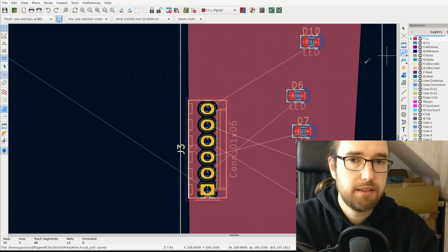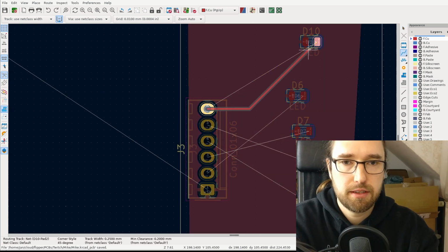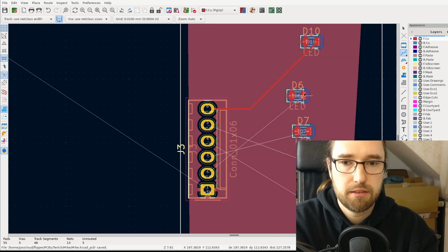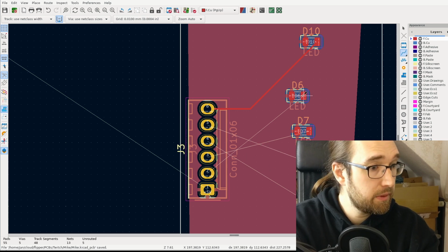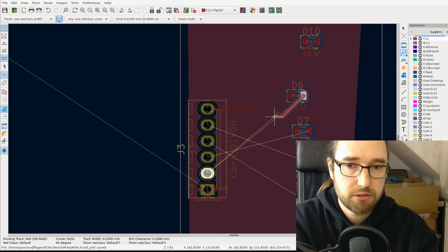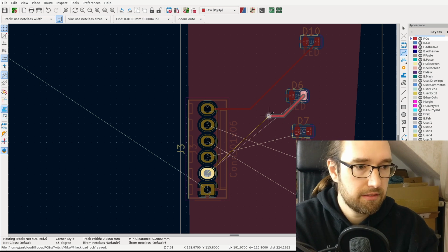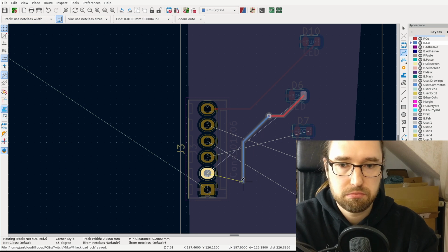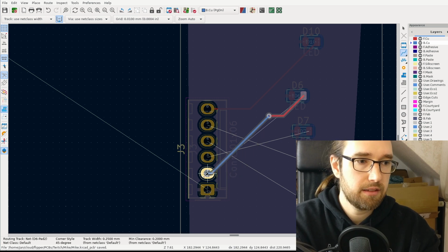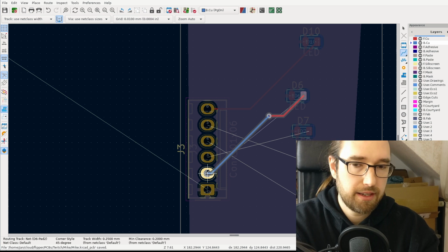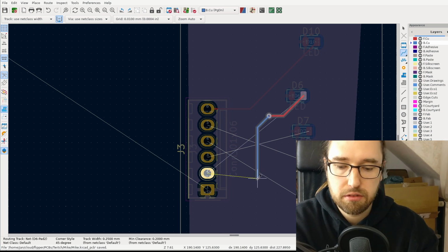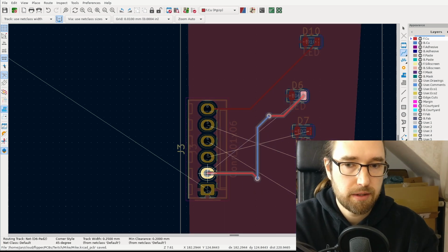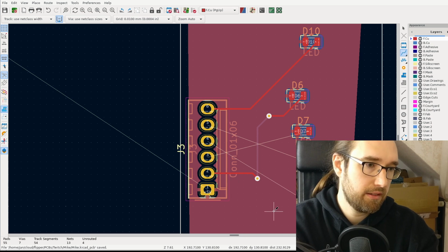But instead here you would do something like, okay, this one, that's fine. We can do that. This one, it intersects all of those. So luckily we got 2 layers, and I can just press V, and now I got a wire, and now I'm on the other side. And now, since this one is in a through-hole part, I can connect from the other side, or even I can press V again, come up again, and now I'm connected here.